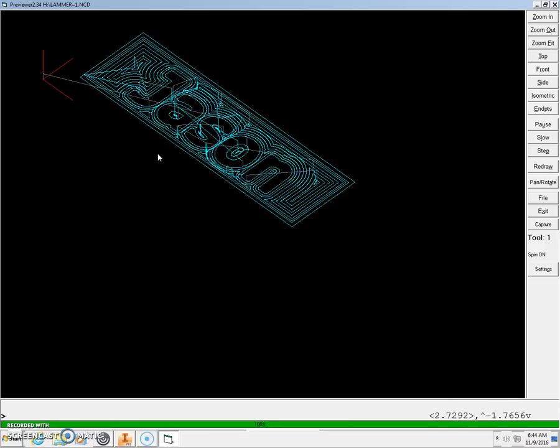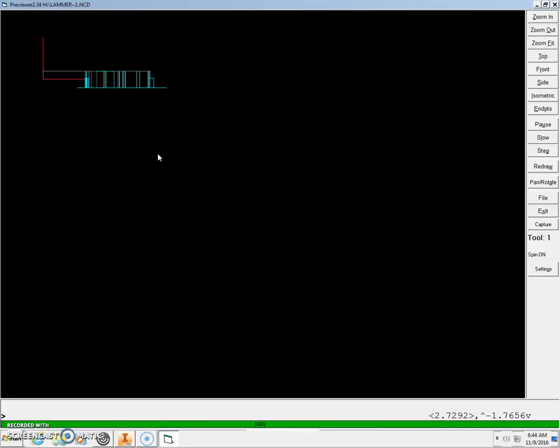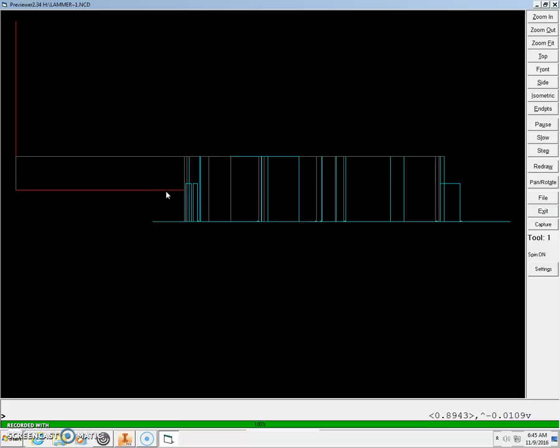Once you have this up on your screen, you're going to stop here, call your teacher over so that they can check your Toolpaths out, and we're going to take a look at the side and view of your part to make sure that your Toolpaths are below the origin. This is what your instructor wants to see. Call them over so that they can check it out, and you can continue cutting your part. Great job so far. Next step is cutting your part on the CNC Mill.